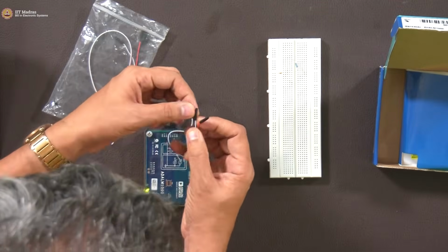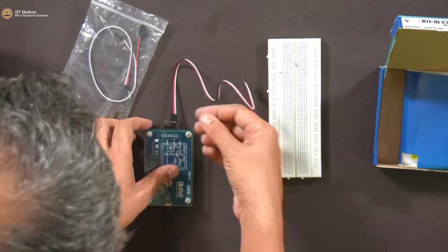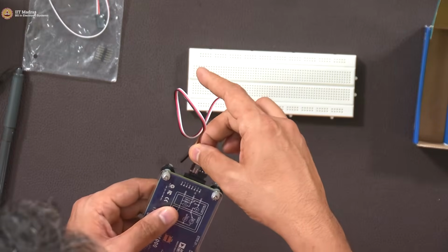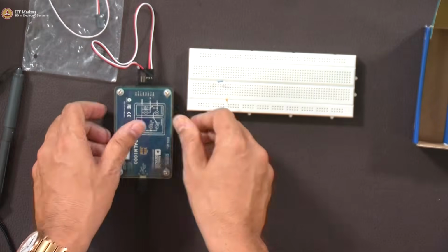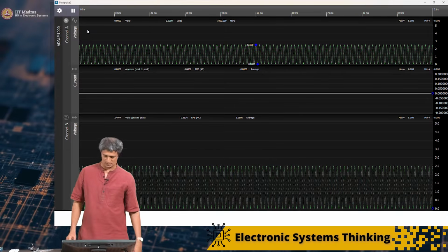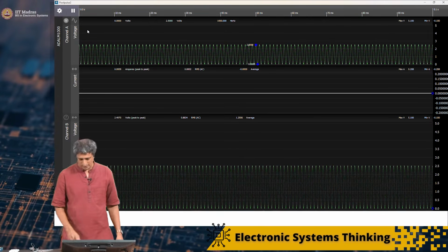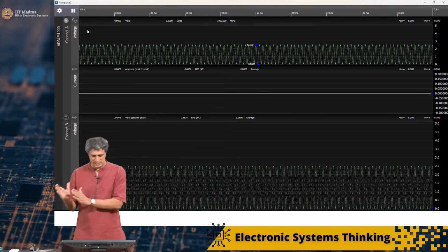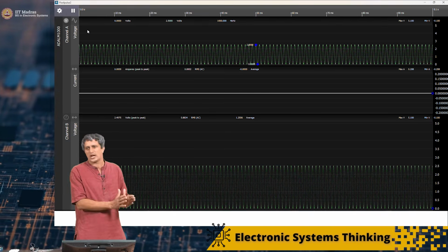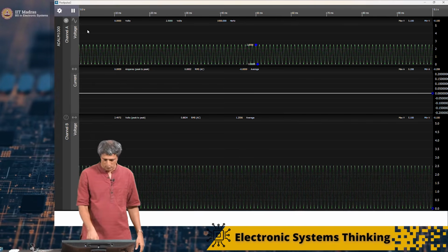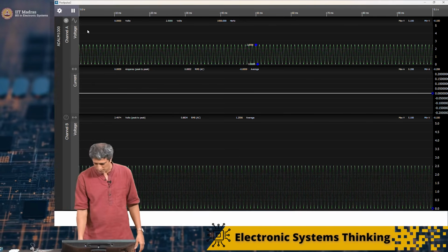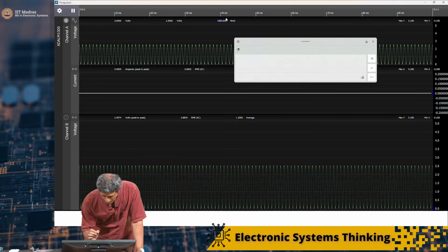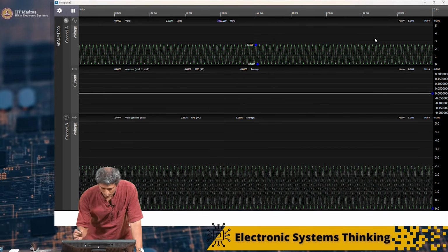So depending on how you connect it, you must be careful. I am going to connect that white wire back to channel B. So what we have effectively done is, we have generated a sine wave on channel A and just connected channel A output to channel B input, and that is why you see the waveform here appearing immediately. Here now, for example, I can alter the frequency.